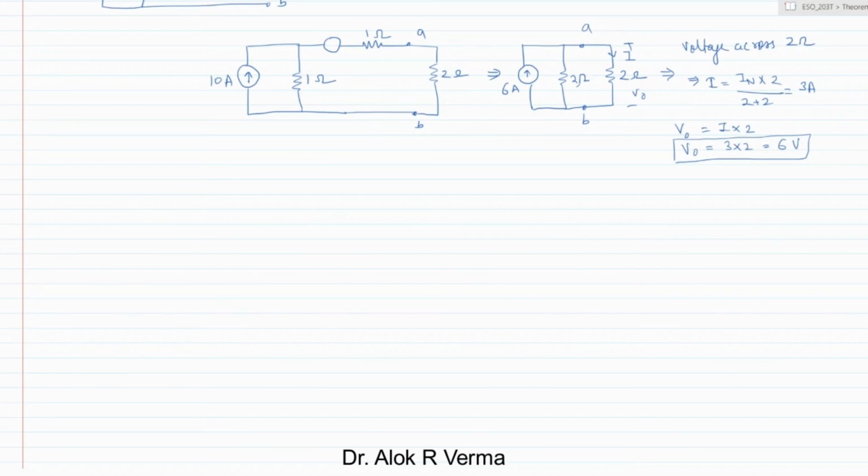The quantity on which the dependent source depends should be unaltered, and using superposition, mesh analysis or nodal analysis, you have to keep that source into consideration. Superposition is only valid for independent sources, and the dependent sources are kept in the circuit as they are during the application.